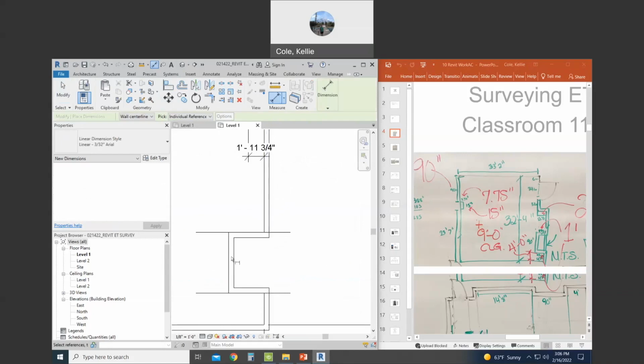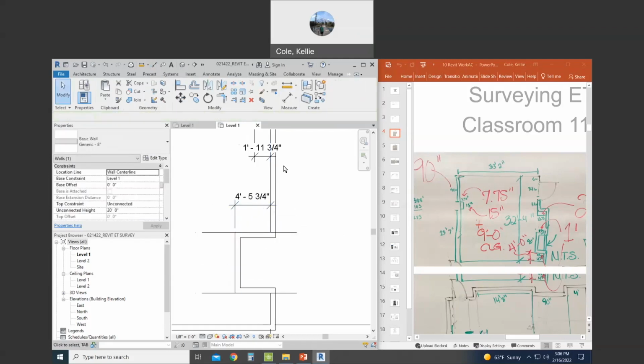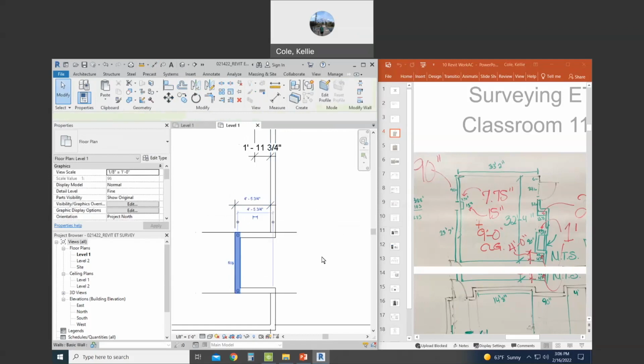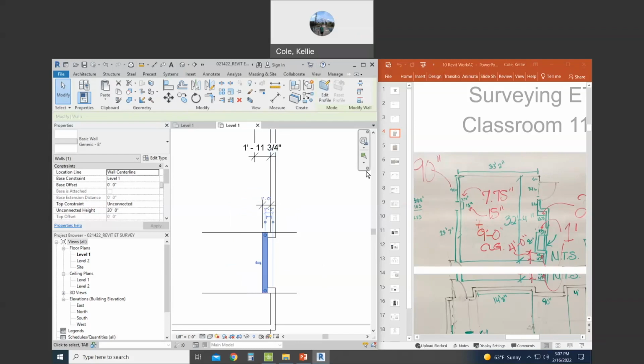And you're going to dimension the face to face. And remember, we can use tab and just hover our cursor around the edge we want to dimension to. Touch there. Tab. Touch the front of that face. Drag our dimension out and click again. I'd like that wall to be 1 foot projection. So I'm going to touch the shaft wall, the vertical one, then touch the blue dimension, type in 1 foot, enter.